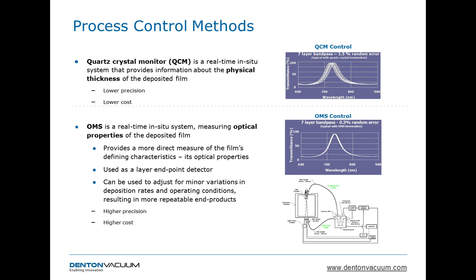Or we can have a witness crystal, which we monitor with a single wavelength optical monitor. We monitor the properties of an individual layer. Both of these types of control systems provide a more direct measurement of the film's defining characteristics, the optical properties. In both of these cases, they can be used as endpoint detectors.